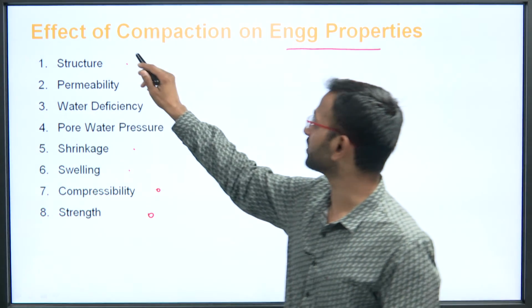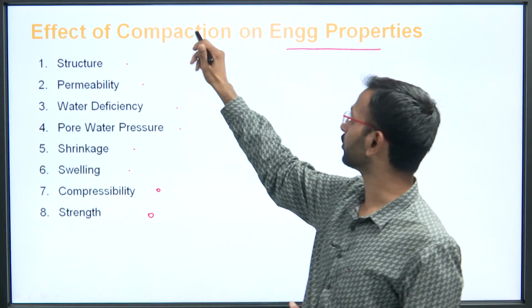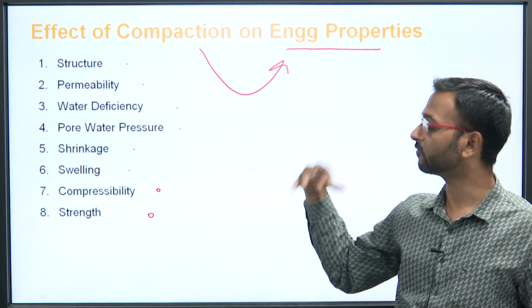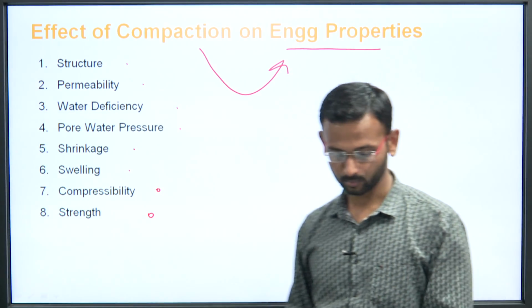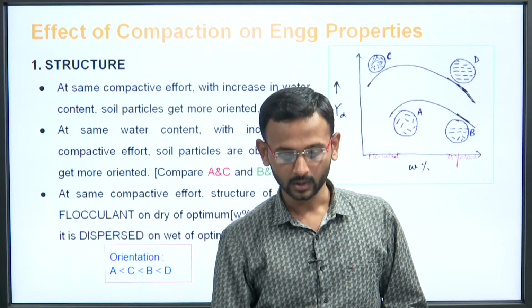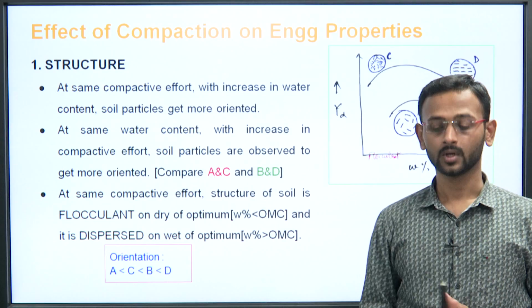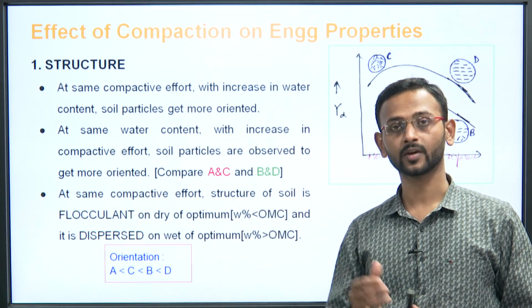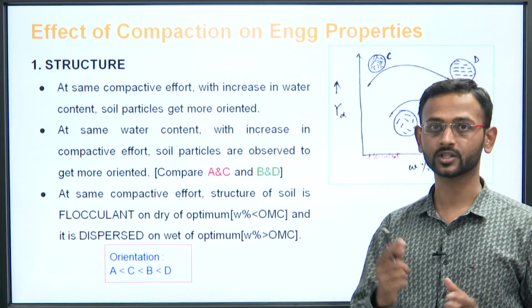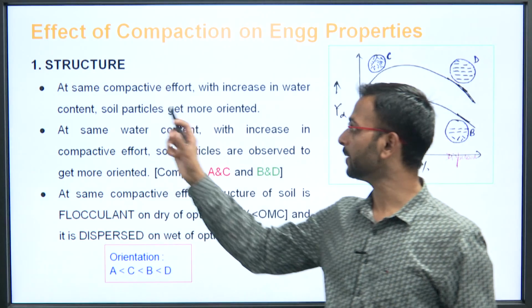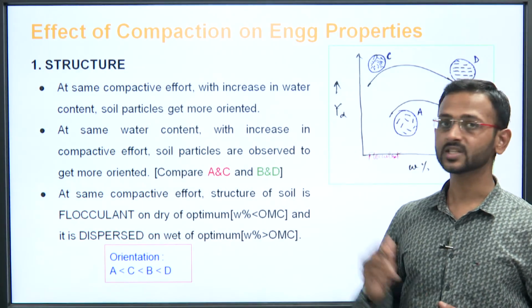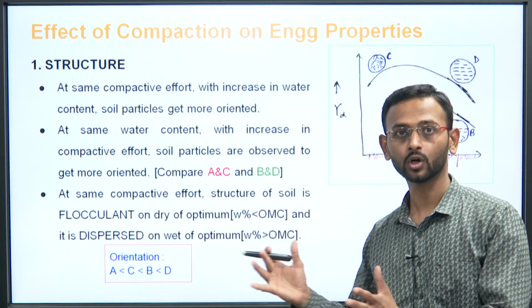Now if compaction is done, what will be its effect on the engineering properties, that we will be studying in this topic. See the very first thing, the structure. We have already studied the structure when we talked about the clay mineralogy and soil structure part. So see here, at the same compactive effort, with increase in water content, soil particles get more oriented.